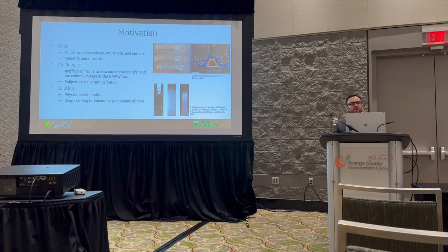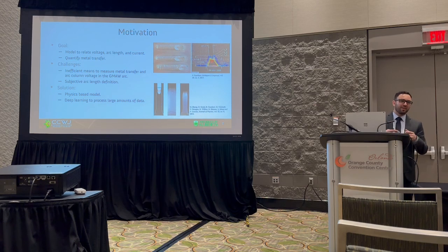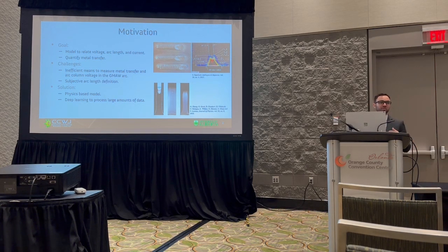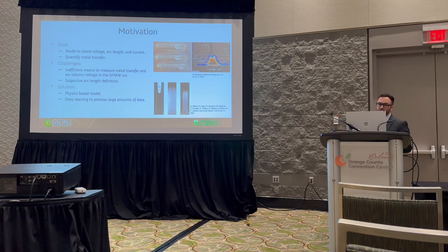When we're doing welding research, specifically with gas metal arc welding, we acquire a lot of data through high-speed videography. When we're looking at these high-speed videos, we're often limited to a qualitative analysis. So the intent here is to ask how we can quantify the data that we're obtaining from these videos. The goal is to develop this model so we can correlate the voltage, the arc length, and the current, as well as quantifying the metal transfer.